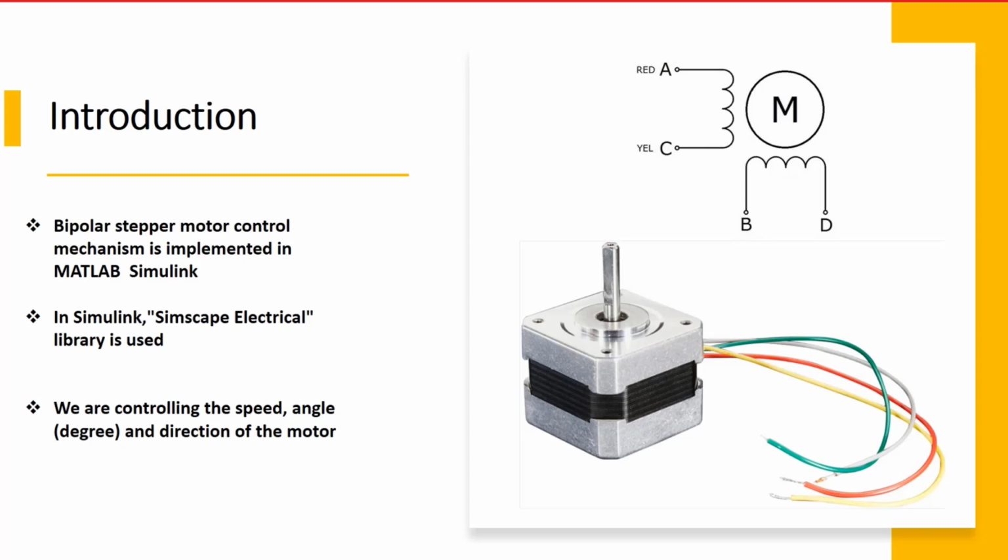To control the action of this motor, we need a specific motor driver. We have followed the mechanism of the L298N motor driver and implemented the motor's control mechanism for a bipolar stepper motor in MATLAB Simulink. We were able to control the speed, angle of rotation, and direction of the motor with our controller.